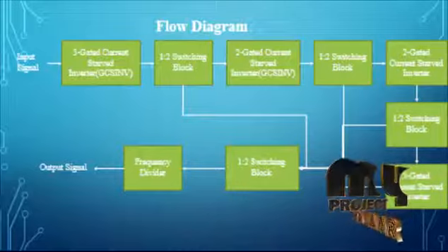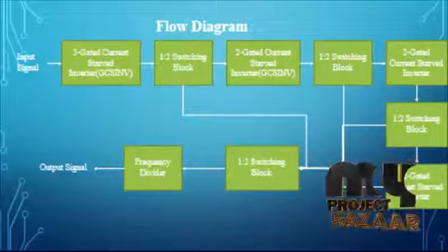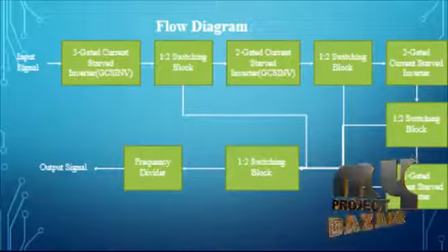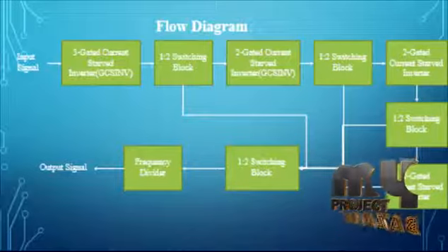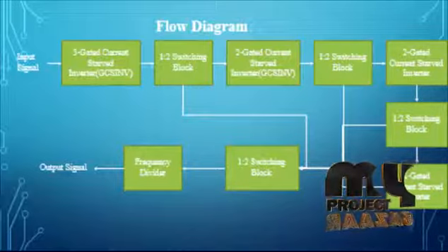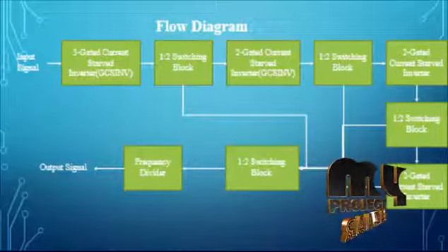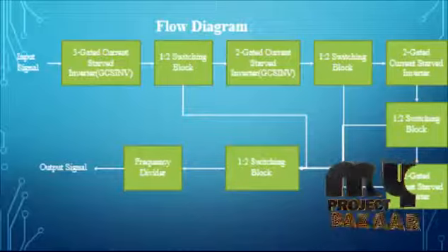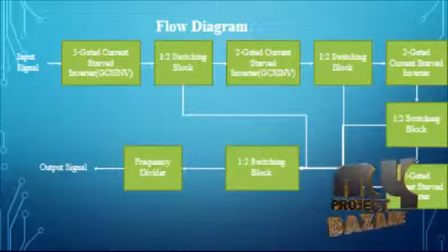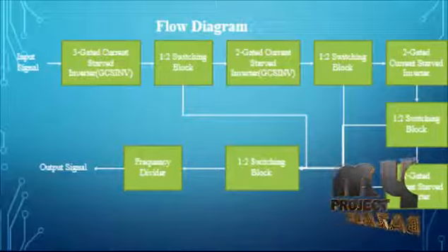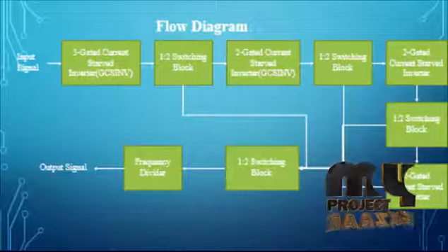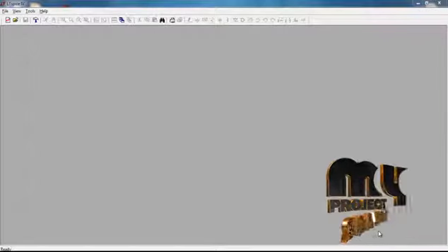This frequency divider is implemented using a D flip-flop. They are called divided by 2 D flip-flops, denoted as DP2. The output can be selected from the oscillator or any of the DP2 circuits. The resulting output frequency is the frequency of the oscillator divided by 2 to the power of the number of DP2 stages, 0 to 7. Now we are going to discuss the running procedure of our product.